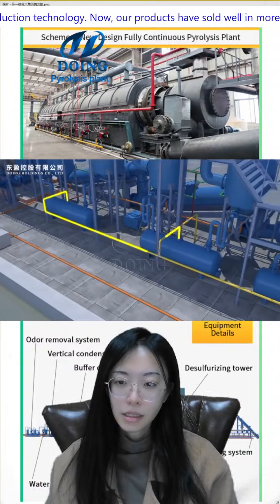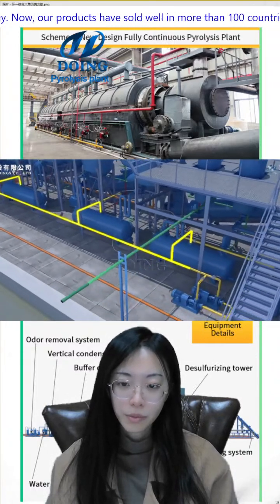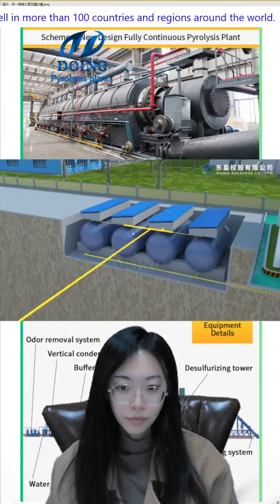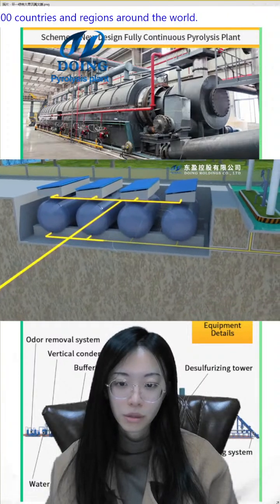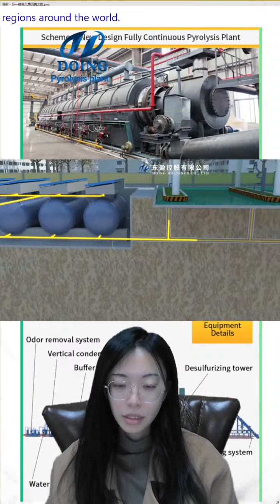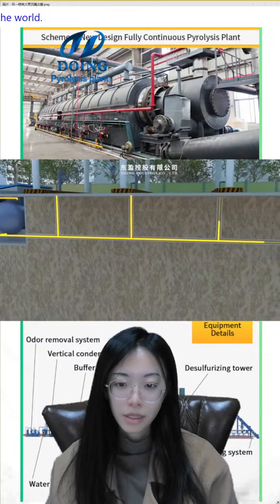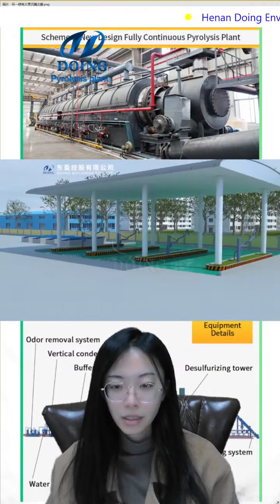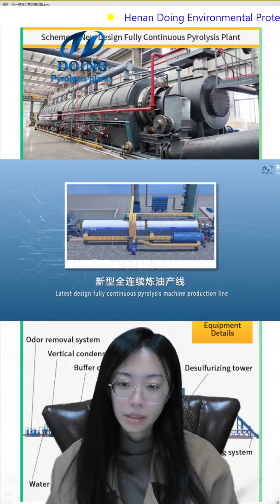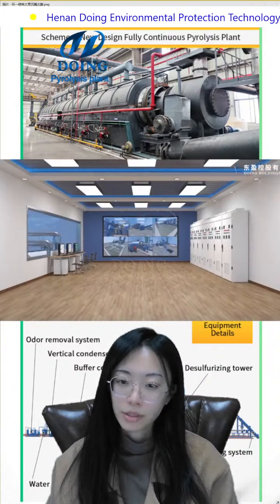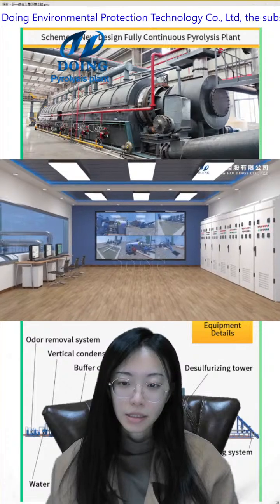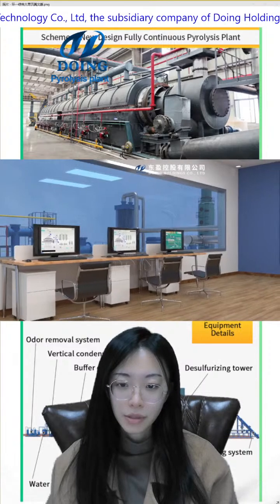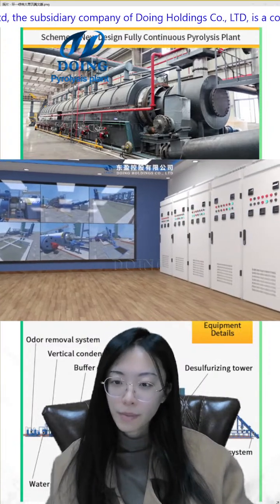And this is the last step. We use an oil pump to pump them into the large storage tank. And this flue oil, we can use it directly, or we can refine it to diesel, and they can use it at the agricultural machine, cement factory, and the ferry, or some mining machine, truck, this kind of places, or oil generator. This is the application of our flue oil, and this is the detailed technique of the fully continuous pyrolysis plant. Any questions you have about this?